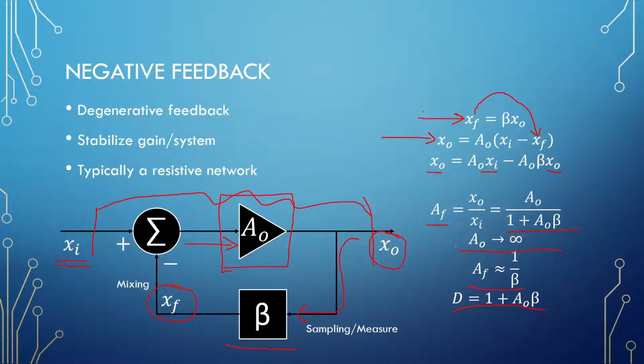So if the gain of the amplifier is large enough, the feedback gain will tend to be 1 over beta. Okay, so there are cases where the op amp's gain is not high enough, and applying the resistors you will not get the gain that you are catering for with your resistive network.